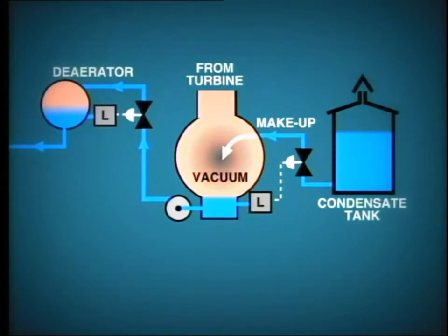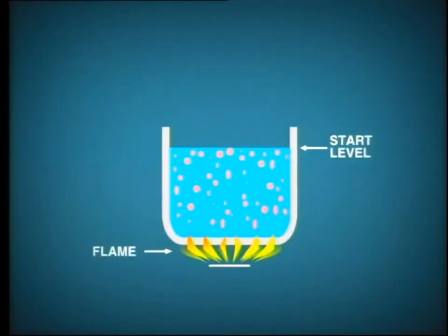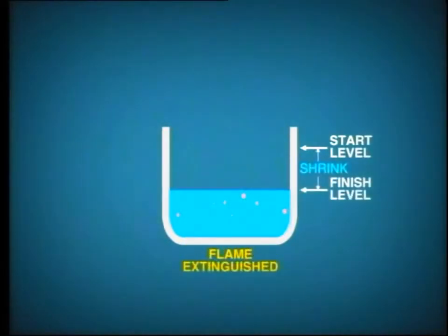In a similar manner, the flow of water into the de-aerator is determined by this particular control valve, which is controlled by signals from the level transmitter at the de-aerator. Let's see how this simple arrangement works during a plant shutdown. As we begin to reduce load on the turbine generator and boiler, we find that the level in the de-aerator begins to fall. The reason for this is that as the production of steam is reduced, a certain amount of shrinkage takes place in the boiler.